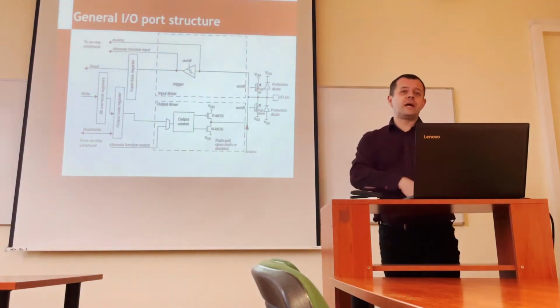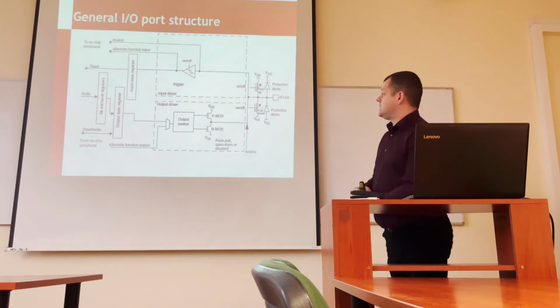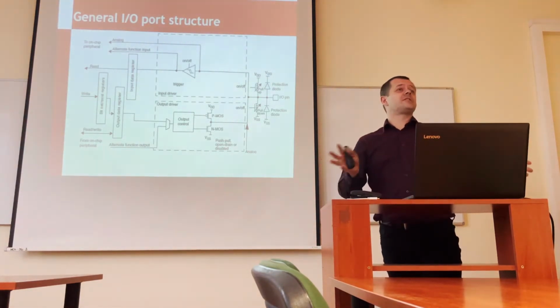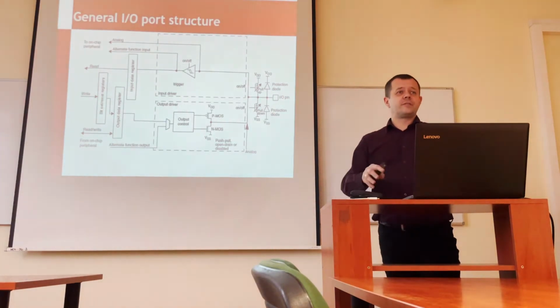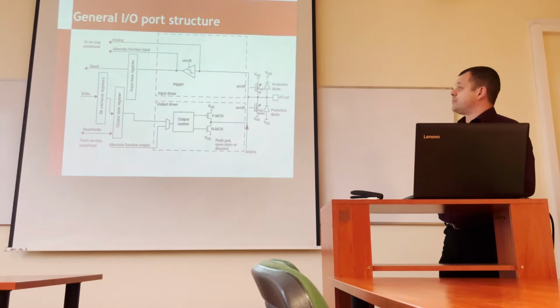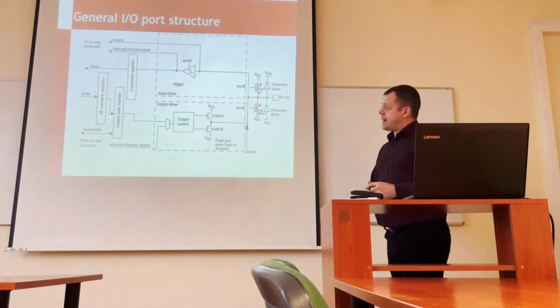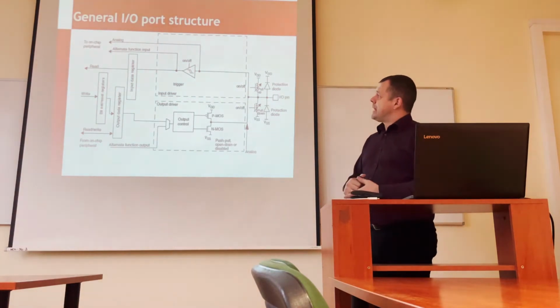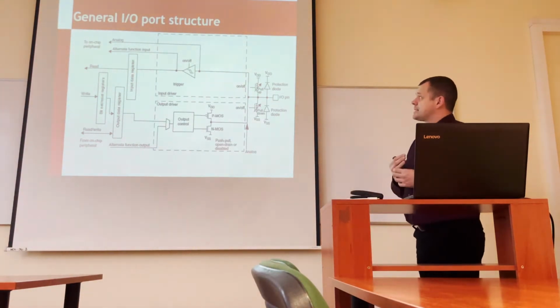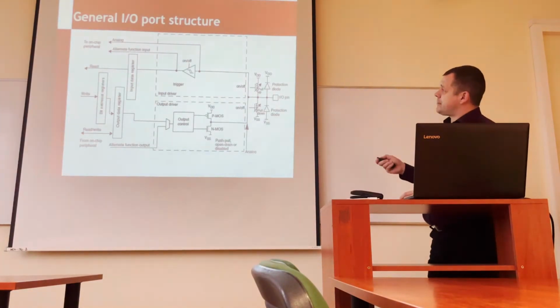driving the pull-ups, pull-downs, switching on some alternate functionality, but this is optional. Those registers differ from microcontroller to microcontroller, but those two registers for writing and reading, and for setting the directivity, are always present. Why do we need to set the directivity?